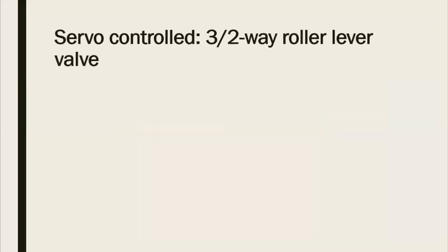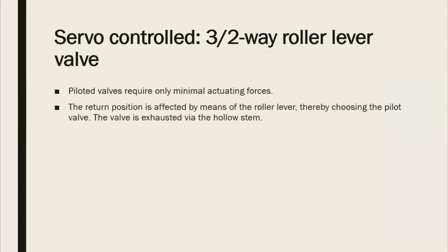Servo-controlled 3-way roller lever valve. Piloted valves require only minimal actuating forces. A small hole connects the pressure connection 1 and the pilot valve. If the roller lever is operated, the pilot valve opens. Compressed air flows to the diaphragm and actuates the main valve disc.